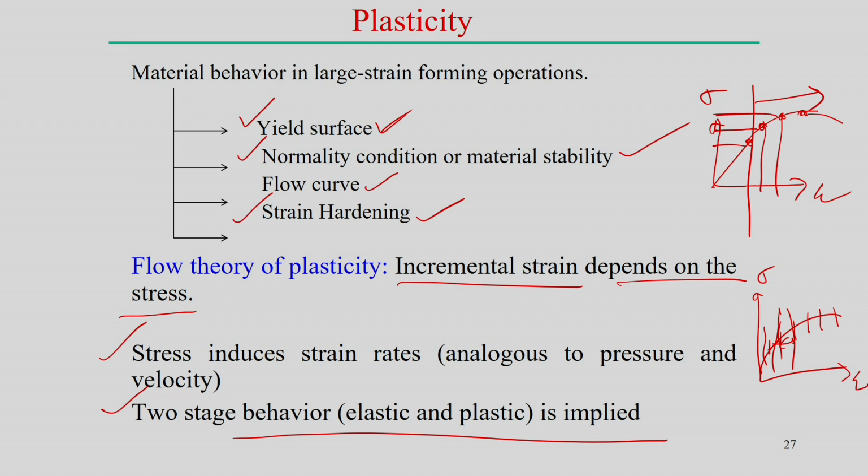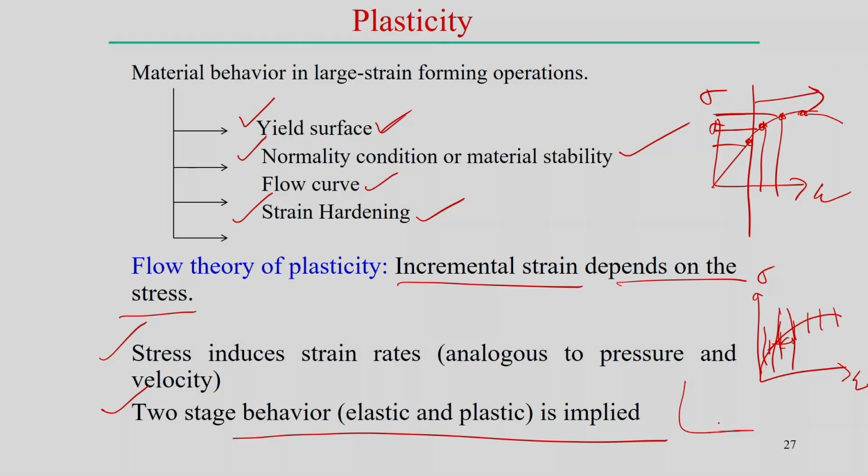But of course, that elastic spring back effect is basically nothing but the material having some kind of elastic component. As we already discussed, even if you are in the plastic deformation zone, when you remove the load at a particular point, there will be some recovery. That recovery is because the material has some amount of elastic properties.